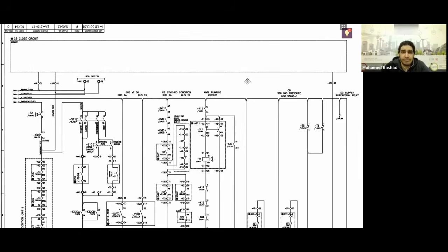Someone is asking about emergency, whether it refers to storing another station. Emergency means you have several modes. I told you to close from the cell itself by pressing select close local, which is the place of the old control room. Remote means from the substation automation system or SCADA. So here, the word emergency, engineer, means that naturally you should always close from SCADA, from SAS, from remote locations.